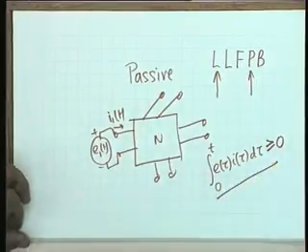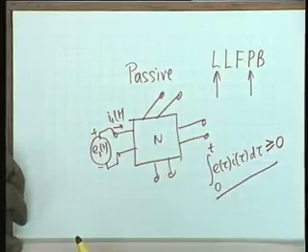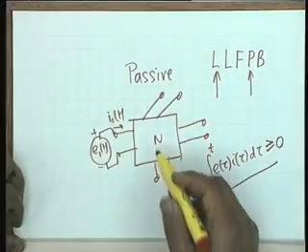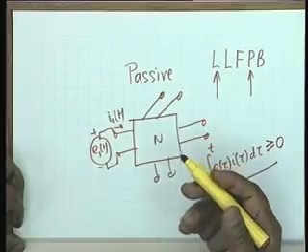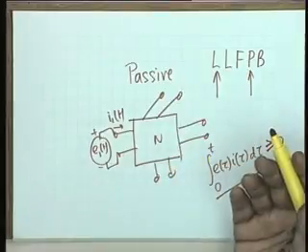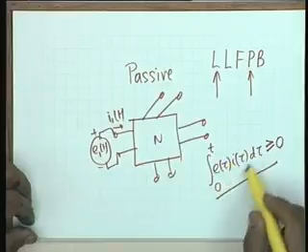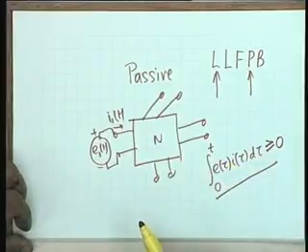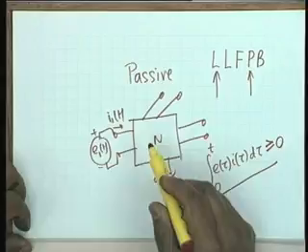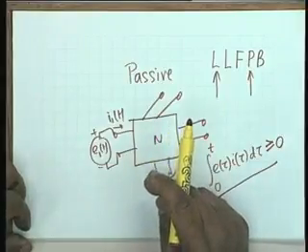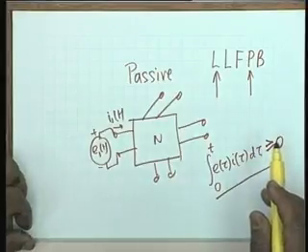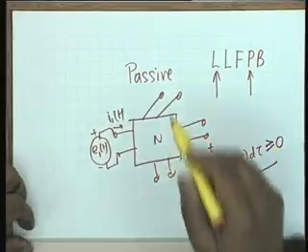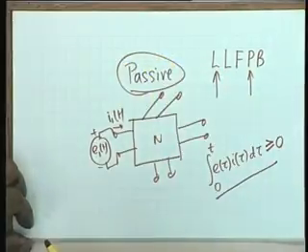If this is greater than or equal to 0, with the network initially relaxed, because if it has energy sources inside, then obviously the network can give out energy, that is, this integral can be negative. So, the condition is that with the network initially relaxed, if this energy integral is non-negative, it can be 0, then the network is called a passive network.